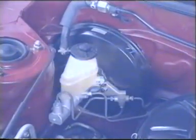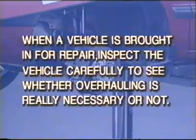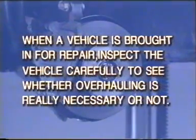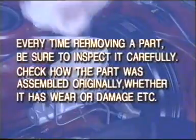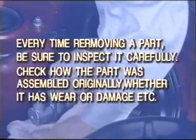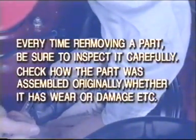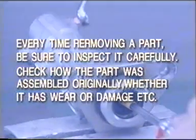The following precautions must be kept firmly in mind when overhauling. When a vehicle is brought in for repair, inspect the vehicle carefully to see whether overhauling is really necessary or not. Every time removing a part, be sure to inspect it carefully. Check how the part was assembled originally, whether it has wear or damage. This is important because some of the causes may be here.